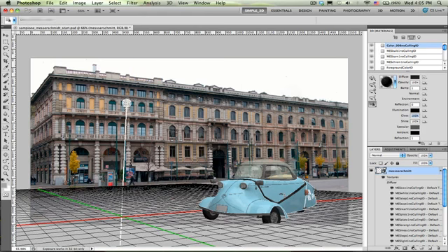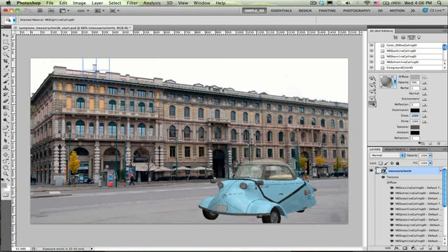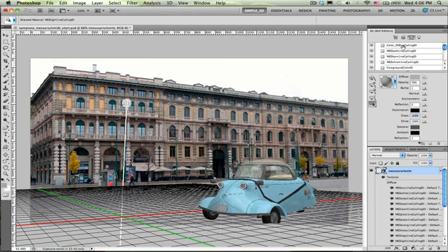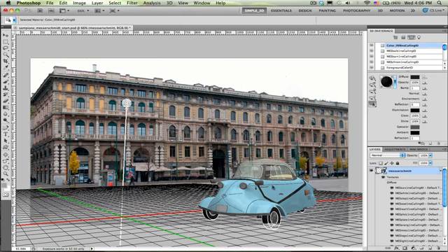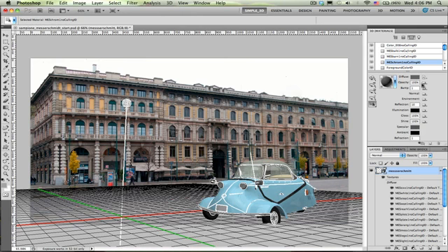Okay. The next thing is I'm going to go through here and just click on the different parts of the car and change the reflective properties that I don't want. Let's first get back into interactive mode because I don't need to ray trace this right now. Alright, so choose the lamp there and maybe give that 5. Choose this part, it's kind of a plastic part. Reflection 5. This black band here, let's give it a reflective property of 7.